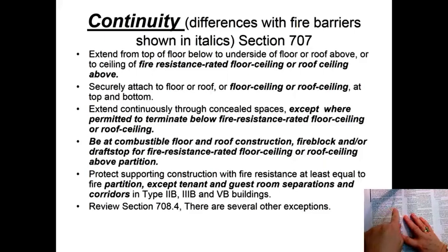It says shaft enclosure shall have a fire resistant rating of not less than 2 hours where connecting 4 stories or more. Basically, what they're talking about could be an opening of stairs, or an elevator shaft, any of those that we're looking at.